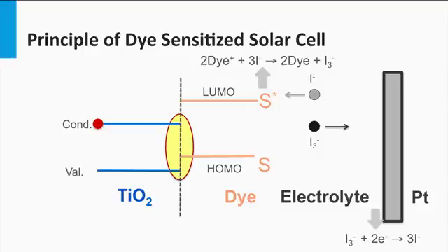This negatively charged triiodide moves to the counter electrode where it is reduced using 2 electrons into 3 negatively charged iodides. These photoelectrochemical cells require a platinum back contact to facilitate the reactions. As a result, the performance of a dye-sensitized solar cell depends on the HOMO and LUMO level of the dye material, the Fermi level of the titanium oxide nanoparticles, and the so-called redox potential of the iodide and triiodide reactions.